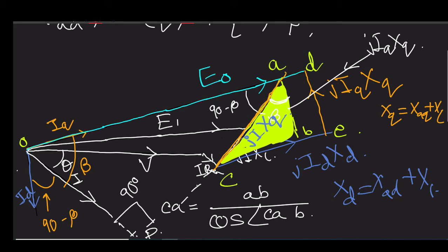So if you are interested in constructing the phasor diagram, nowadays the phasor diagram doesn't make much sense, but it was used at an early date. So you will find this is V, then IRa, then you join jIXq, then you will get a point. This point is also very important. This is known as E dash, or you can say E naught dash. So what is the physical interpretation of E naught dash? I am going to discuss it soon.